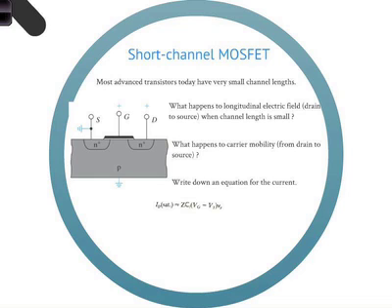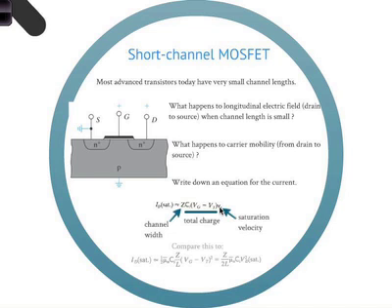Okay? So the ID under saturation, when you have a short channel MOSFET, is essentially Z. Of course, you have to have the Z here because that's the channel width coming out, because C is all with respect to unit area. So Ci, the voltage times Vs, which is the saturation velocity. Channel width, that's the total charge, that's the saturation velocity. And you can compare this to our previous equation we had for saturation. This is what we just derived a couple of slides ago.